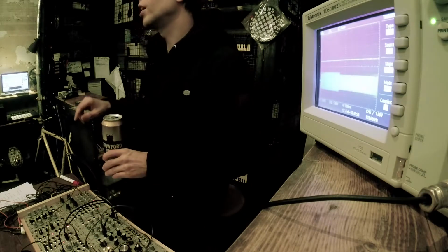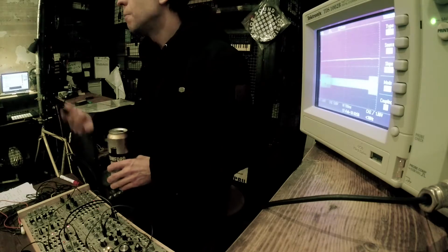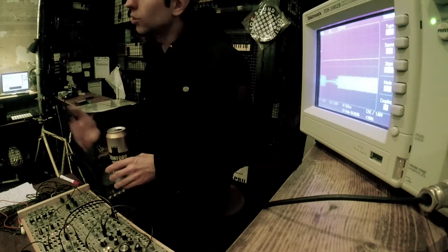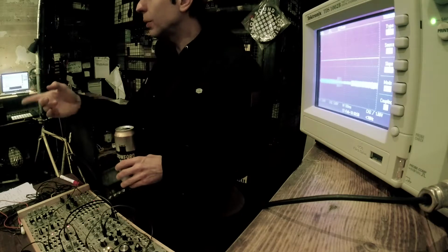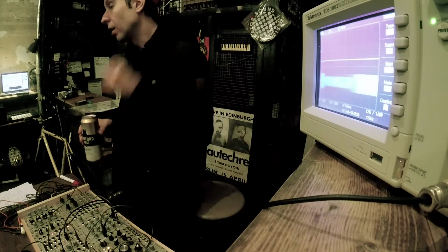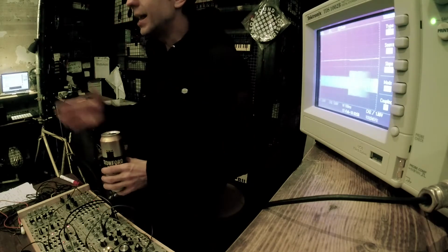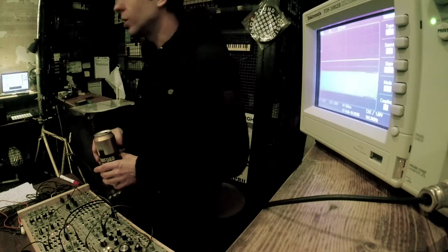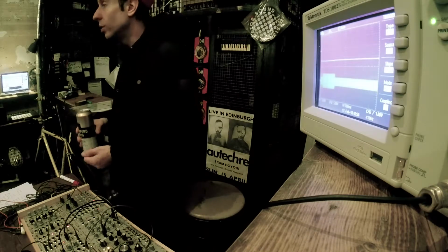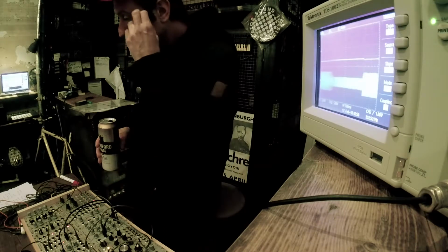Even if I drive the triggering signal higher, I would still get only about 3K, which is funny because I have another module, an offset and gain with slew rate limiting, that also caps at 3K. I think it might have to do with the type of chip they're using.